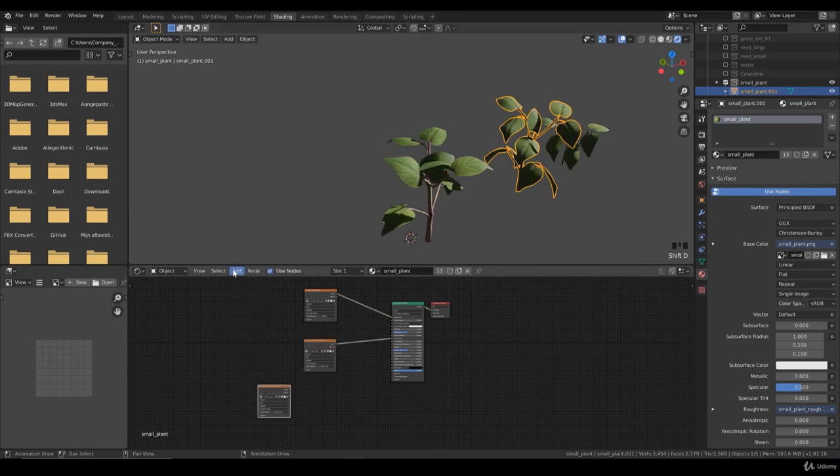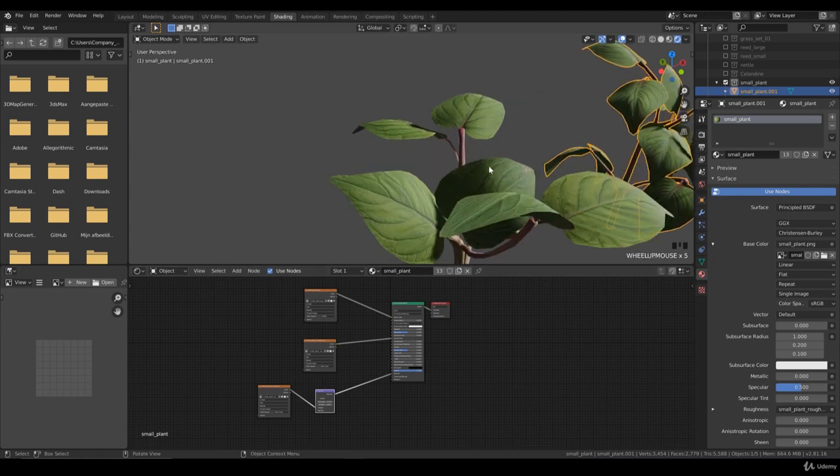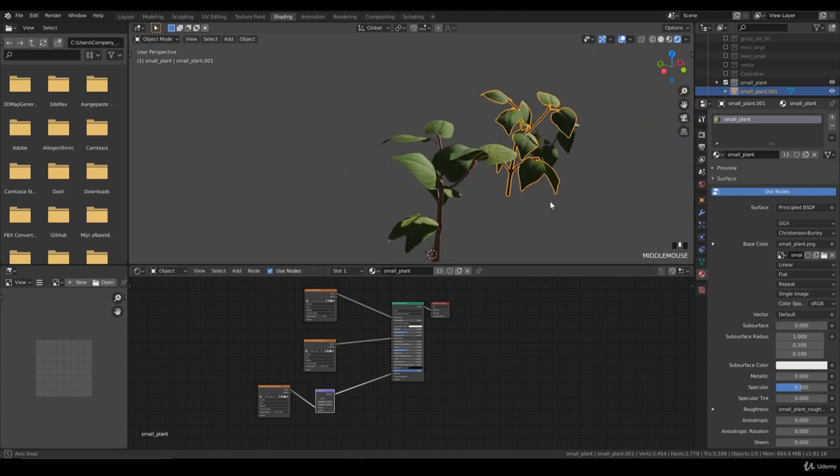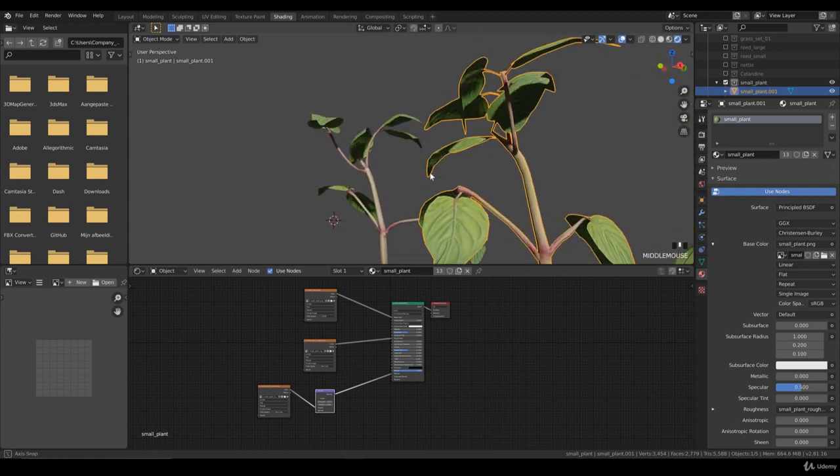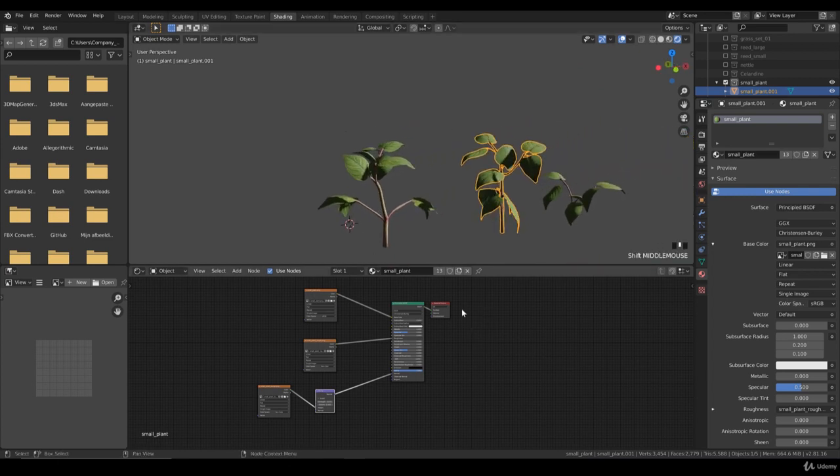And duplicate it again. Add a vector bump. And we want to have the bump image. And I'm going for a very small height value of 0.07. Non-color data, and putting it in the normal. So we have this slight bump effect, but still specularity. Yeah. And translucency.